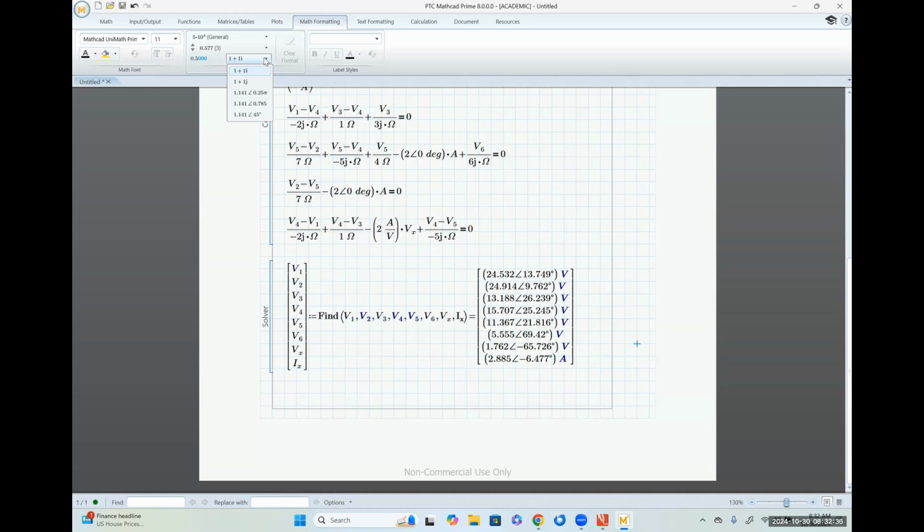Yes, but only, so just to be clear here, if I did J5, that italicized J is not the J that I'm looking for. So it is not interpreting that correctly. So that's why I'm having to do 5J. And then I have to explicitly multiply by my unit in order for it to calculate that or interpret that as an impedance of 5J with a unit of ohms.